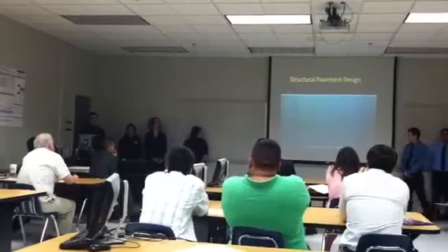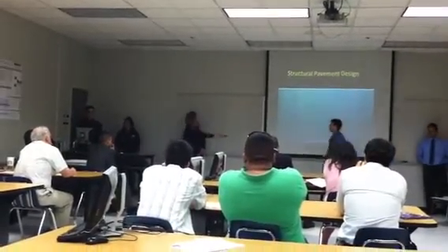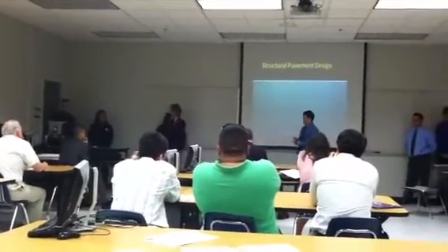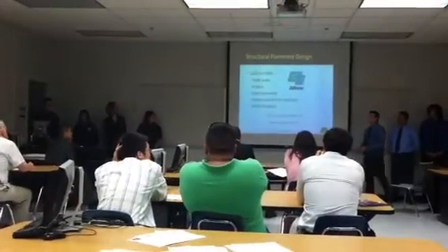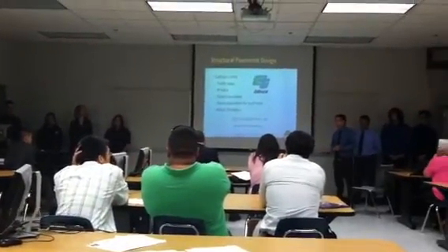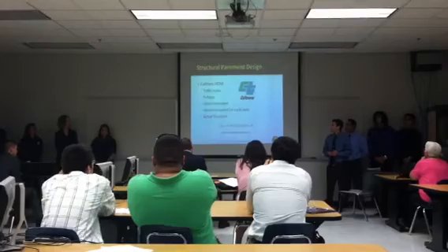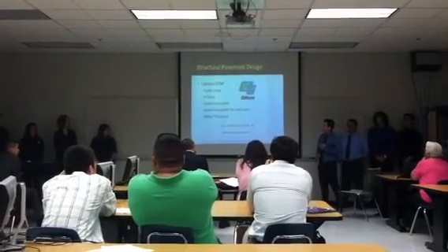And now George will talk about structural pavement design. For our structural pavement design, we elected to use the Caltrans method. Now, in order to use the Caltrans method, we need to know 2 pieces of information. We need to know the traffic index and the R value.